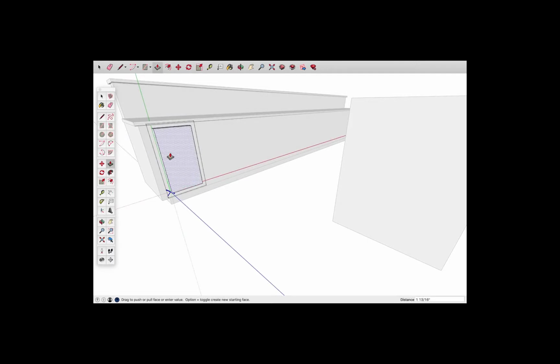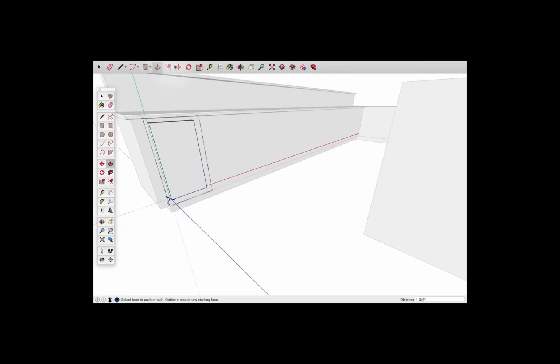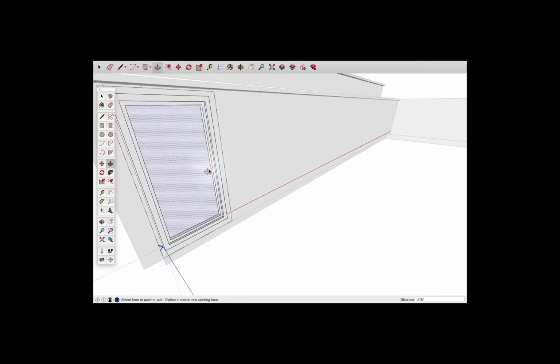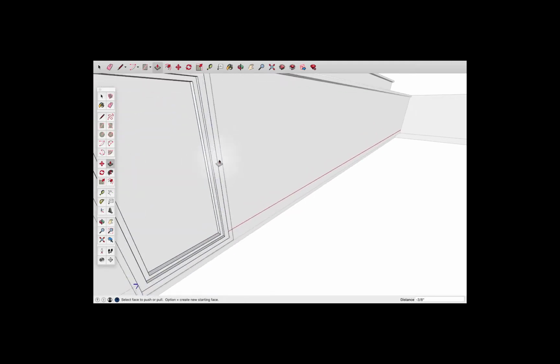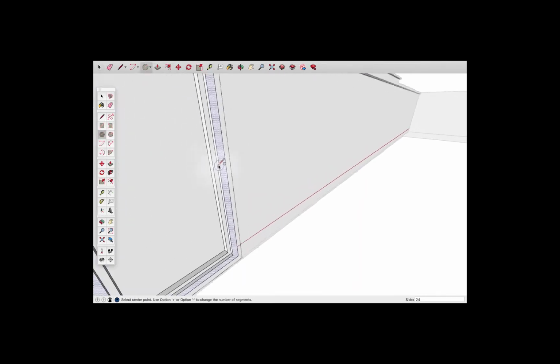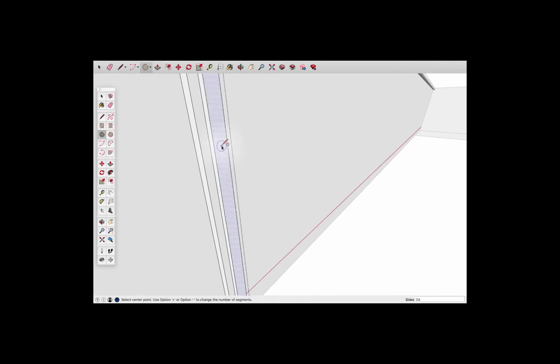And you can pull it out a little bit, and we can even add a little bit of a profile as long as we're here. Just pull this in and this in a little bit. There you go. Beautiful. You know, I could even add in detail for my handle if I wanted to. Let's just put a little kind of knob on there. Beautiful knob. We can pull out the circle.